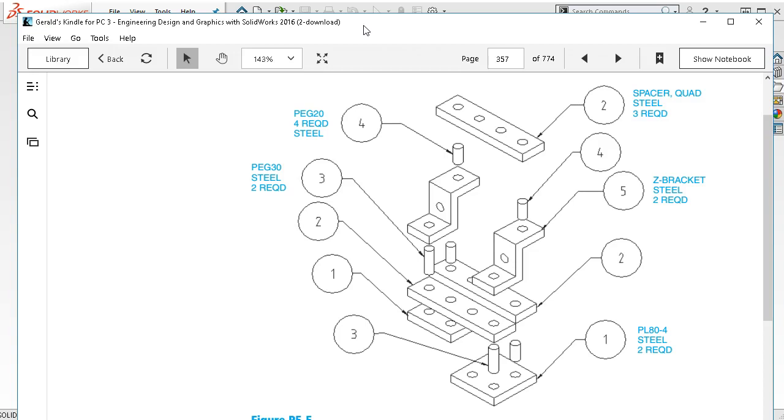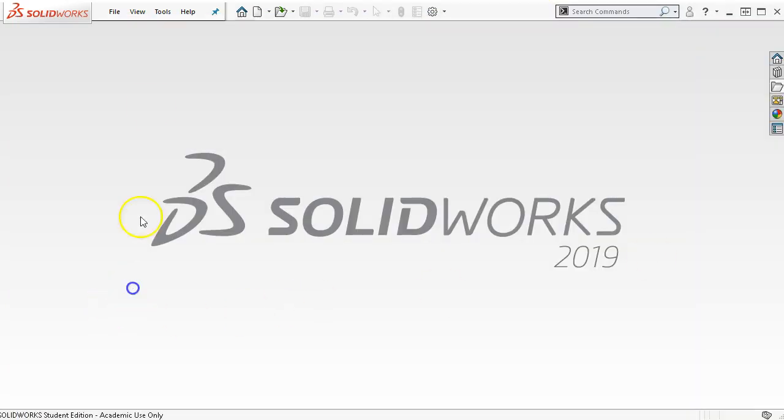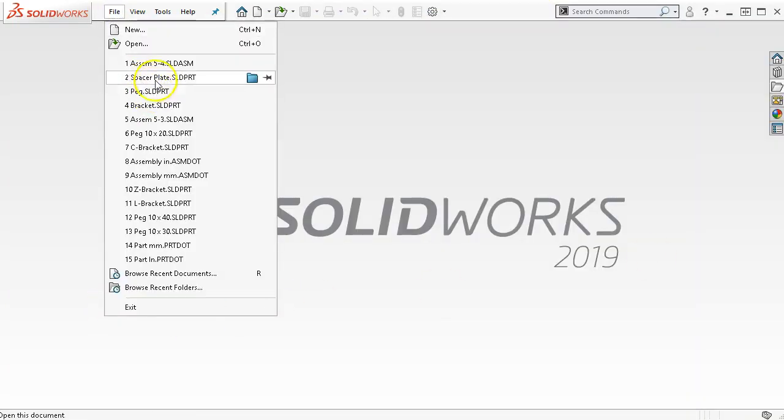Go in and bottom up, top down type assemblies. And once we've created the assembly and we're preparing to go over the drawing, then we can create an exploded view. And the exploded view will be used in the drawing or just as a graphic as part of our process. Okay, so a new assembly.